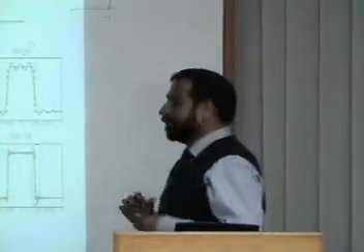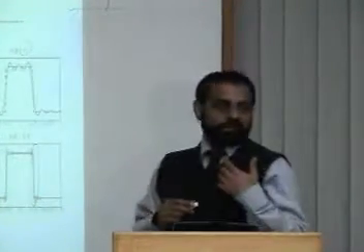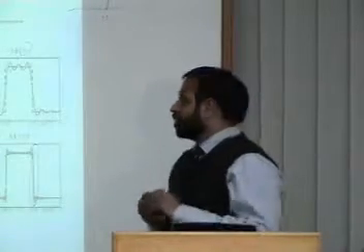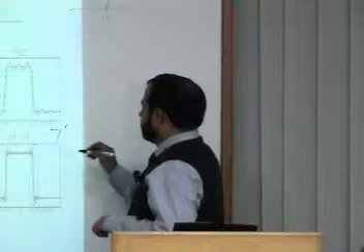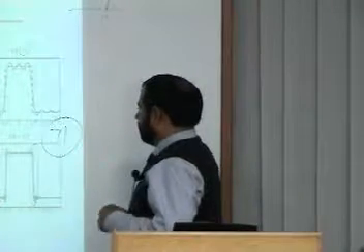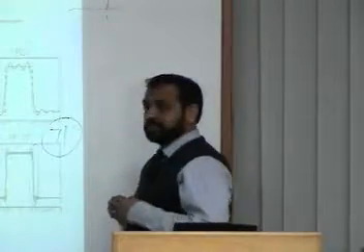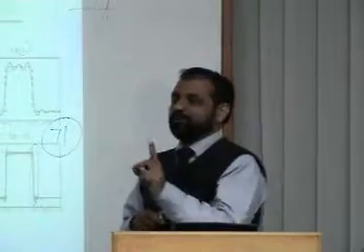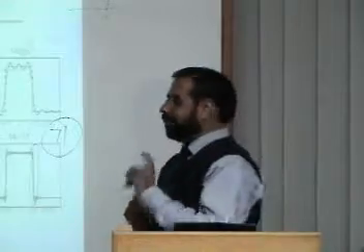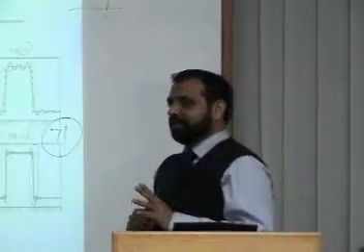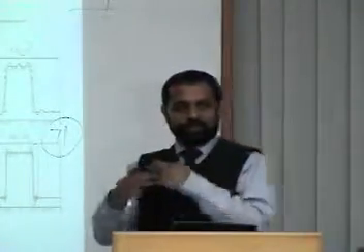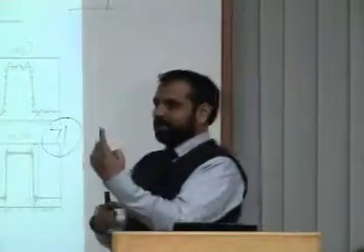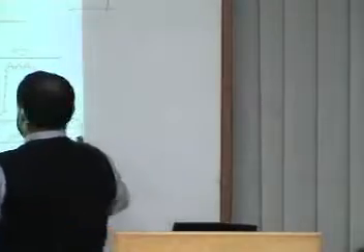But look, 35 on this side, 35 on that side, 70 plus 1 in the center. So it has 71 coefficients. So what does it signify? Cost. 71 multiplications and 70 additions to calculate every output sample. Right? One filter will cost you 71 multiplications. So 71 multiplications, 70 additions, you get one output. Then again you do all that, you get another sample. So this is the cost.